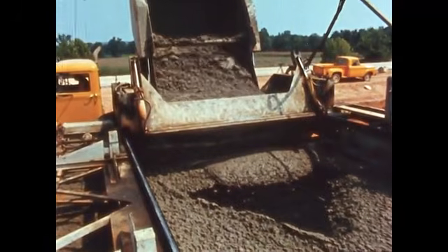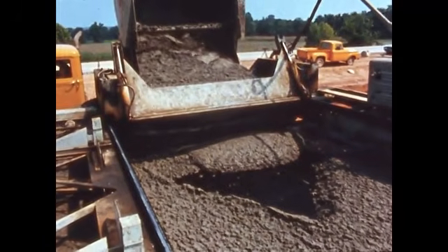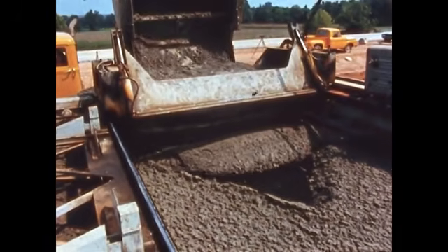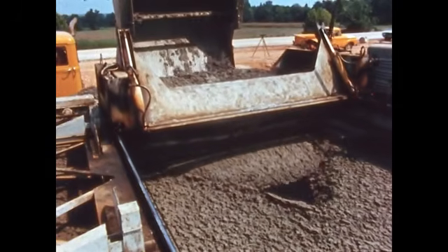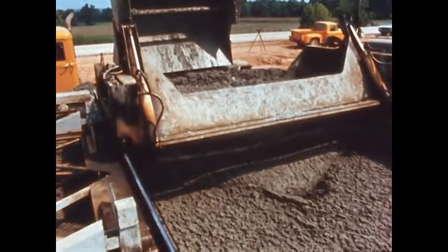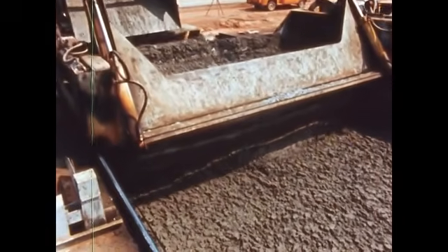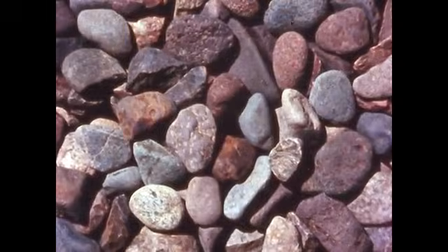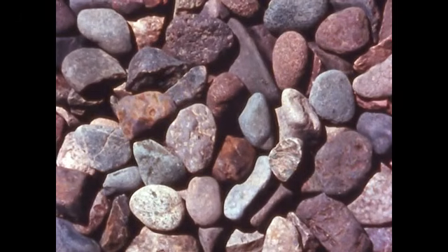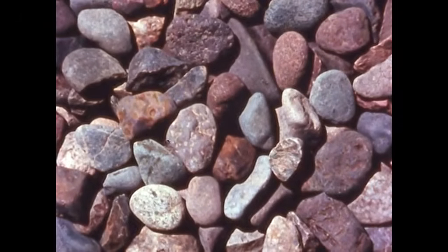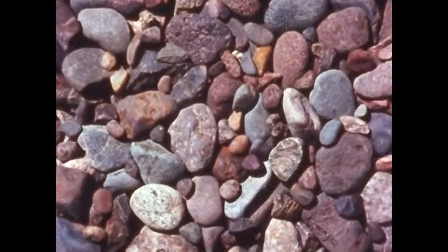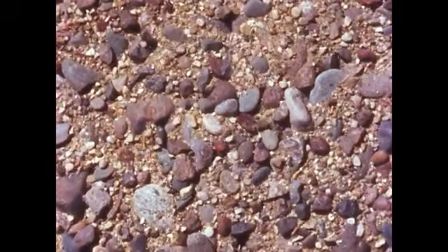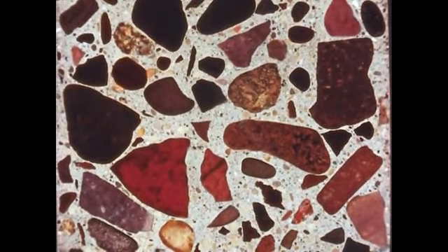If you could look deep into good workable concrete, you would see millions upon millions of pieces of inert material. Each piece, no matter how large or small, is entirely surrounded by a chemically active paste made of Portland cement and water. The aggregate is uniformly distributed. The larger pieces of rock are separated by smaller pieces, which are in turn filled in with sand. And finally, sufficient water cement paste fills all the remaining voids. The aggregate occupies about 3/4 of the concrete mass.